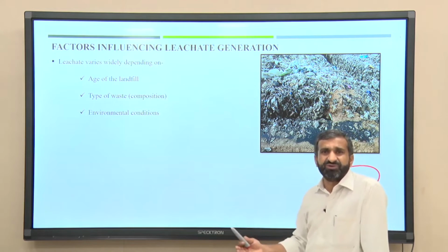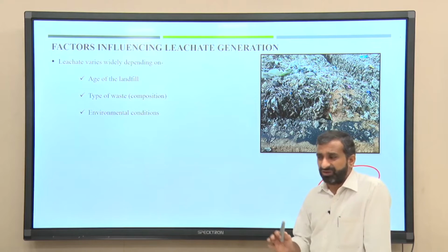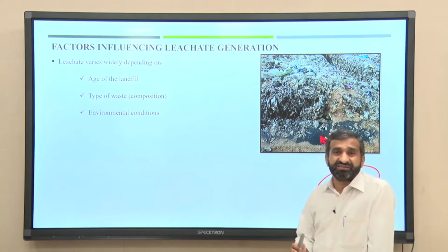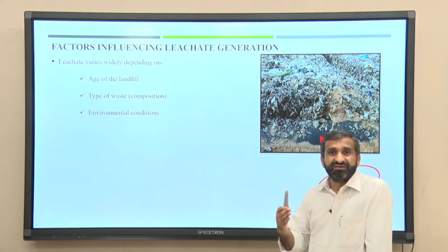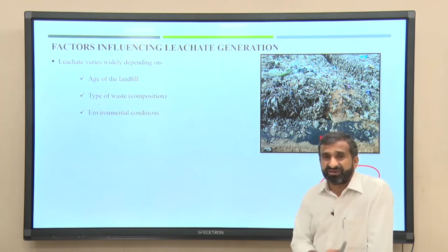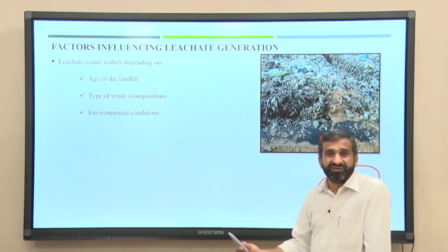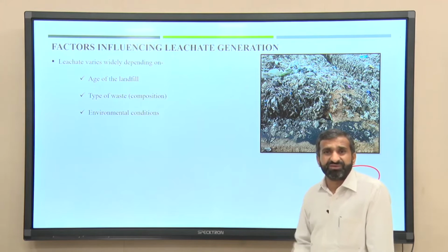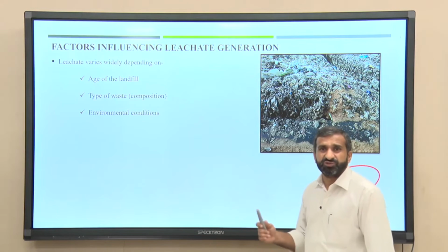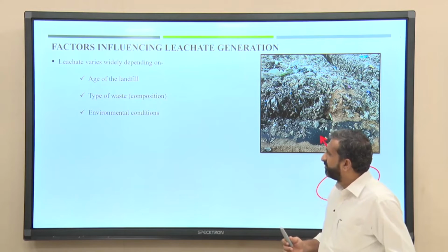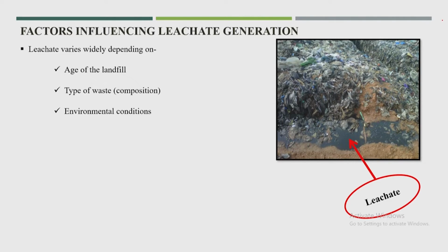You need not worry much about the leachate part, but now mixed kind of waste is reaching, and in a country like India, 50 to 60% is biological waste, or in some other countries the biological waste goes to 60%, 80%. In that case, if the entire waste goes to the disposal site or landfill area, obviously you have to worry much about the leachate. Not only the leachate, but even polluted gas production is a more concerning issue in the landfill area. And the local environmental condition is also very important. Suppose there are nearby habitations, nearby water storage areas, or flood plains. I think these are some important issues that will be more of a concern for leachate production.